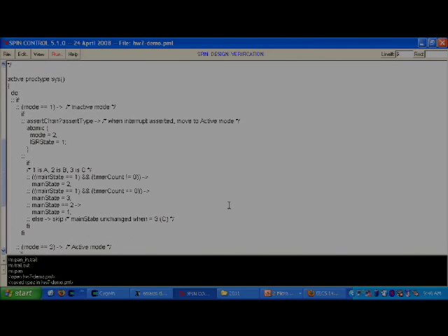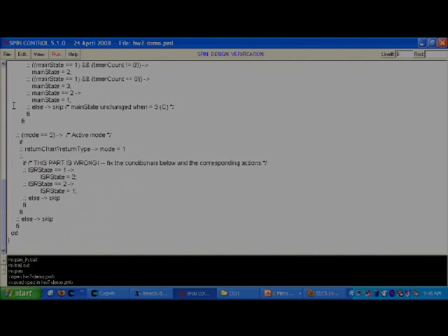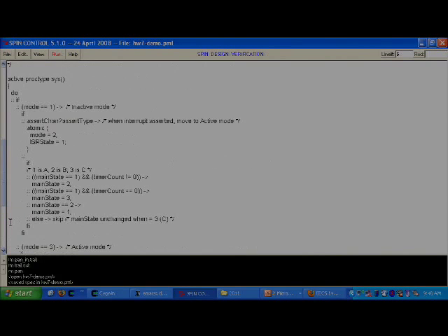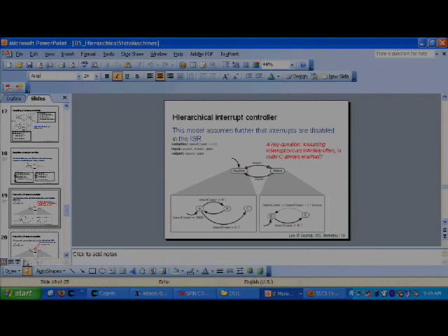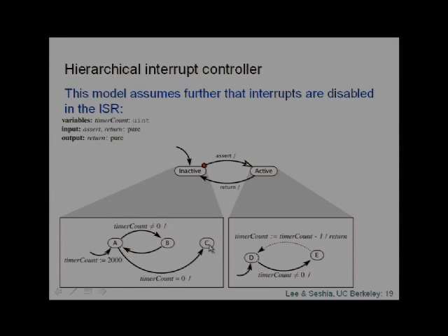So now let's look at the actual model of that hierarchical state machine. It's a process which has an outermost infinite while loop, which makes sense because the state machine runs forever, right? You start it off and it keeps looping between the states. One thing to note is that even though here C is like a dead-end state, we have an implicit self loop here, okay? So once the system gets to C, it just loops in C.